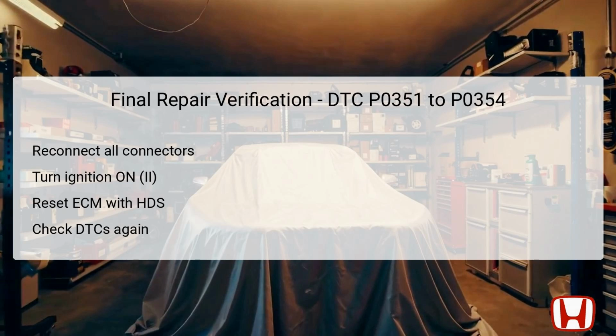Use the Honda Diagnostic System, HDS, to reset the ECM, effectively erasing any previously stored DTCs. Following this reset, you should perform a thorough examination of the DTCs once again to ensure no previous codes are active.